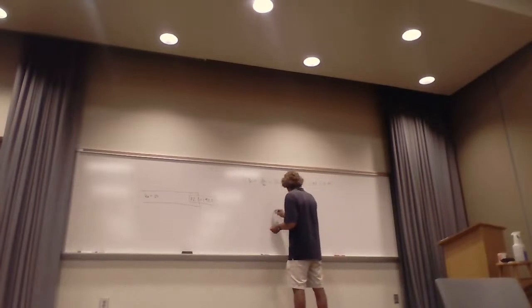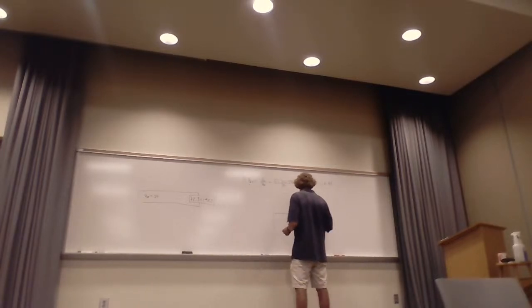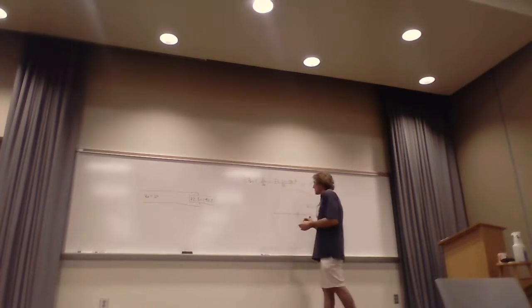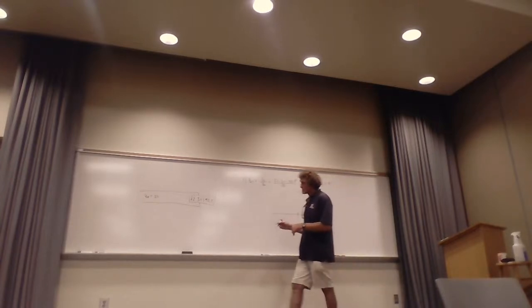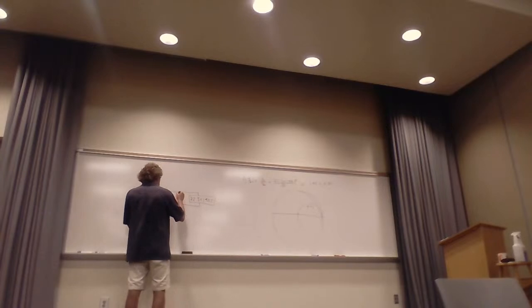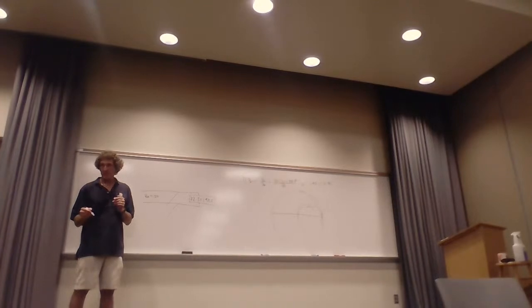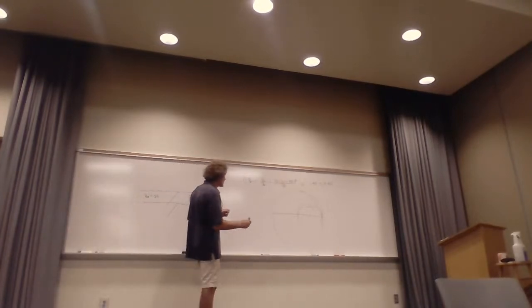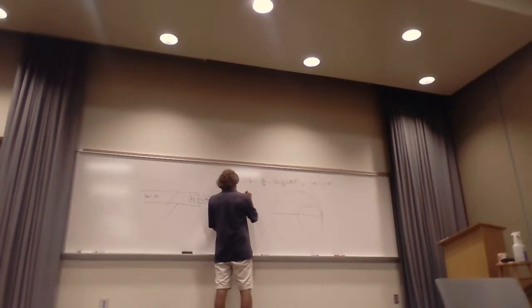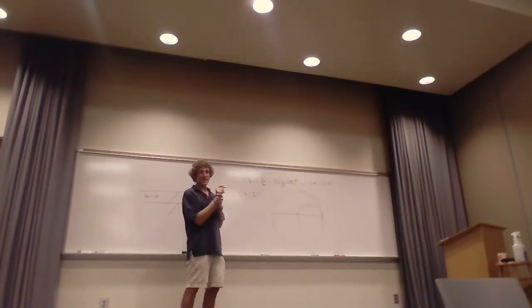So now I draw my Smith chart that hopefully you have access to. You've done these things many times. And here's the R=1 circle. Well, that's the normalized impedance. Because the stub we're going to put on is a shunt or parallel stub, we're going to work in the admittance domain, aren't we? You all remember that? Yeah. All right, so now I have to take 1 over this to get YL, which is 1 over ZL. Does anybody have a calculator so you can give that to me? I can't do this in my head. If it was 1 plus J1, yeah, I can do that, but this I can't.